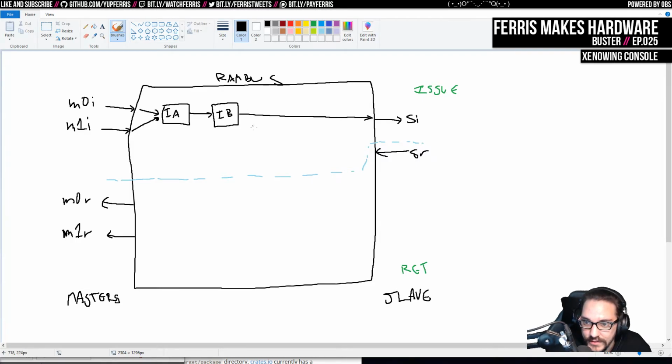So once that's issued, it's going to issue the actual data to issue the read. And that's also going to do some internal bookkeeping in this FIFO here. We're going to call this the Mem FIFO. The idea here is that it's going to issue the read, and in addition to that, it's going to dump whichever master issued that read into this FIFO.